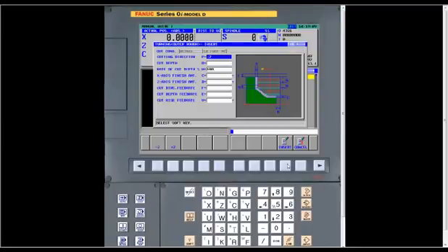Whenever you put information into it, like here, we'll just go Z, Z minus, and then it's asking for a cut depth. And you can see it highlights Q, so that it's the depth of cut per side. This is a radial amount. It's very important that you remember that. It's a radial amount. And once you type in a value there, 0.1, and then you press input right here, it's important that you remember that, because if you try to press insert here or insert there before you put all the information in, you'll get this alarm, short input data. Whenever you see that alarm, that means that you've tried to input the cycle before you put all the information in. That's what that's for.